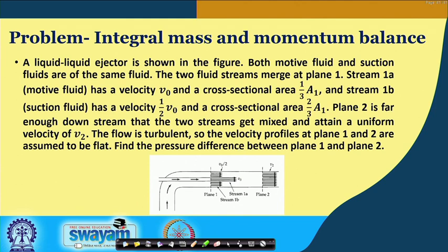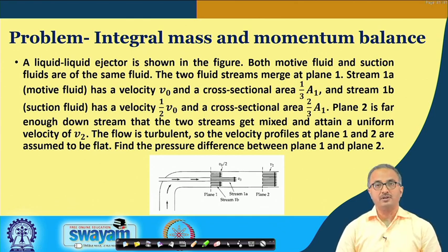Perhaps you know that we use here what we call a motive fluid and a suction fluid, and the working of this particular ejector is based on Bernoulli's theorem, in the sense that inside this thin tube some motive fluid comes through a nozzle, and its velocity increases and that causes a decrease in the pressure, and this decrease in the pressure causes suction of the suction fluid from another channel. So this is broadly the working of a liquid ejector.